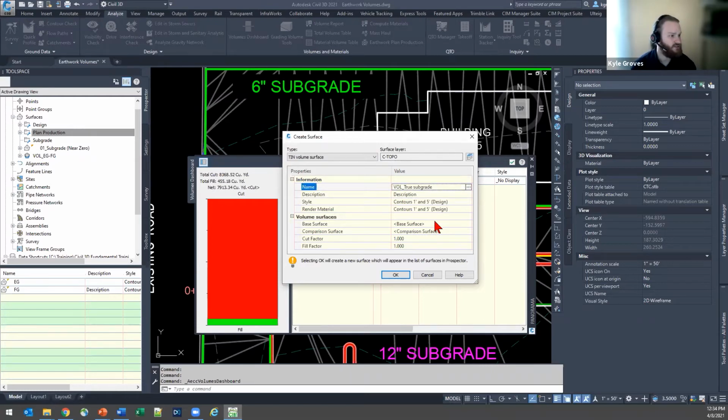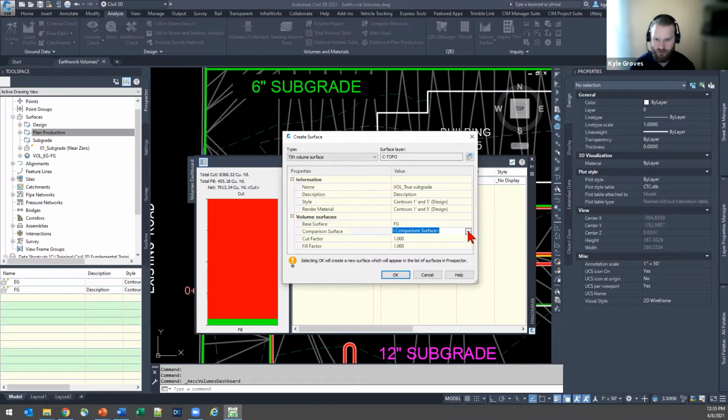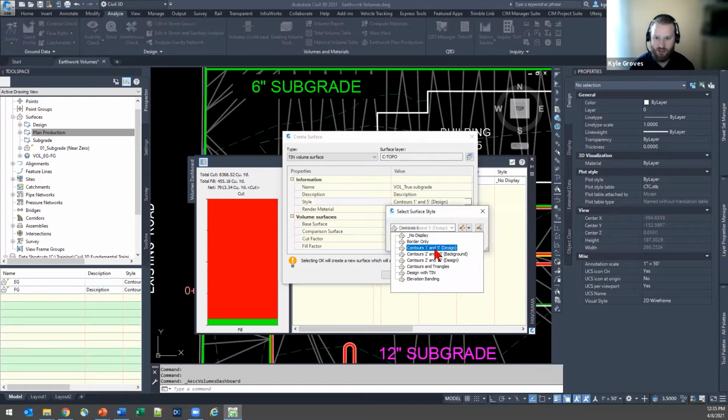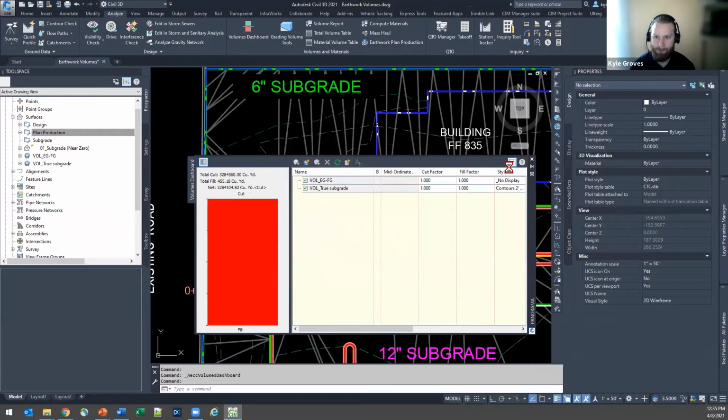Now, for my base surface, this one is going to be my FG, I believe. And my comparison surface is going to be my subgrade near 0 surface. And we're going to check this. And the style for this one, I just need it to look different so that I can compare them in Object Viewer. I'll give this a background style. So FG, subgrade near 0, we'll say OK.